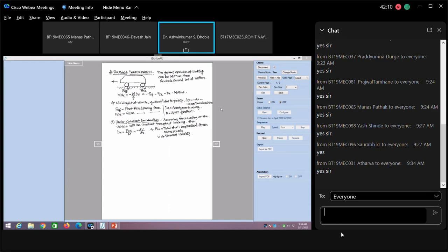So sir, now let us integrate this. About the equation, as Fxt is constant, we have assumed that the braking force is constant throughout the braking. So if you integrate, then from here we can write, integral dv from v initial to v final is equal to minus Fxt by m, because we have assumed that it is constant, from 0 to ts, this is the dt.